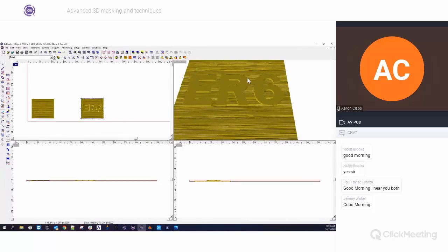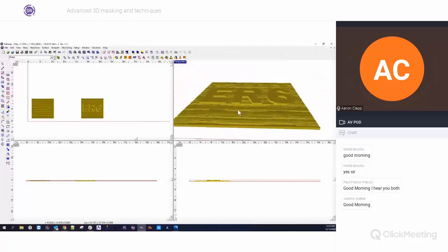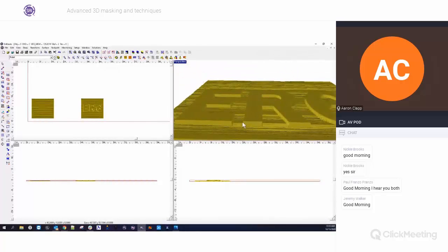The other problem is that this looks pretty good here in the perspective view in terms of how sharp these corners look and how nice and even they are. They're not terribly slanted or anything. But as the tool on your machine cuts through this and ramps down right here, you're actually going to get a little bit of a curvy spot right here where the bit is not able to hit it, because it's moving too quickly and then has to drop suddenly.